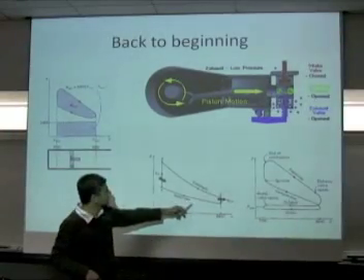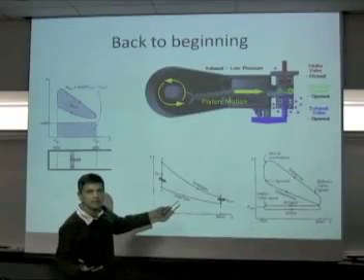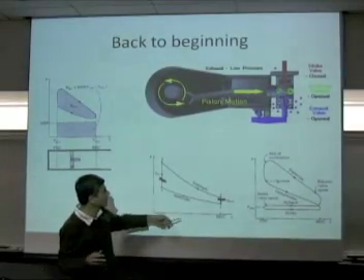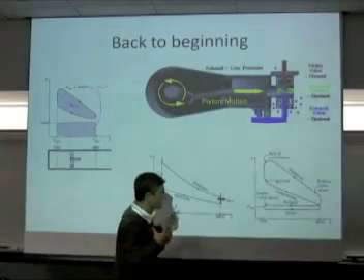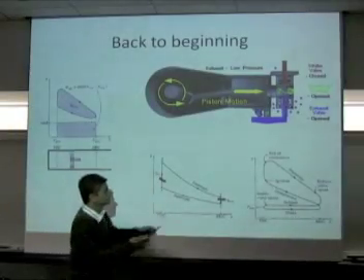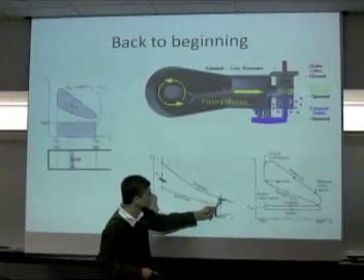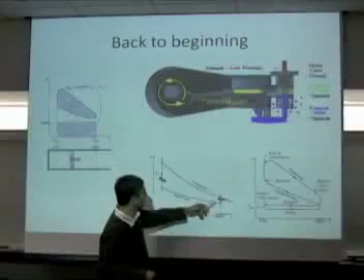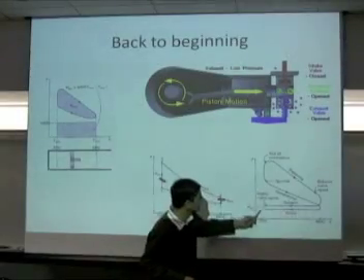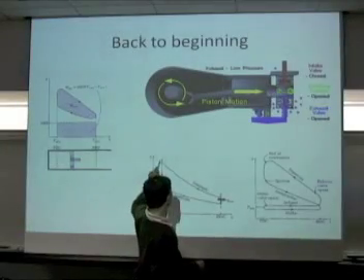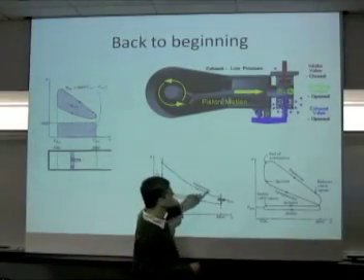But in reality, it doesn't happen, because whatever air comes into your engine is actually exhausted at the back of your tailpipe. So you basically have what is called an open cycle. The air that's coming in at 1 is not the same as the air leaving at 4, so you get an open-ended cycle. And in reality, this is what happens in the engine also, because it doesn't have sharp corners like here, where it reaches a certain pressure and turns immediately.